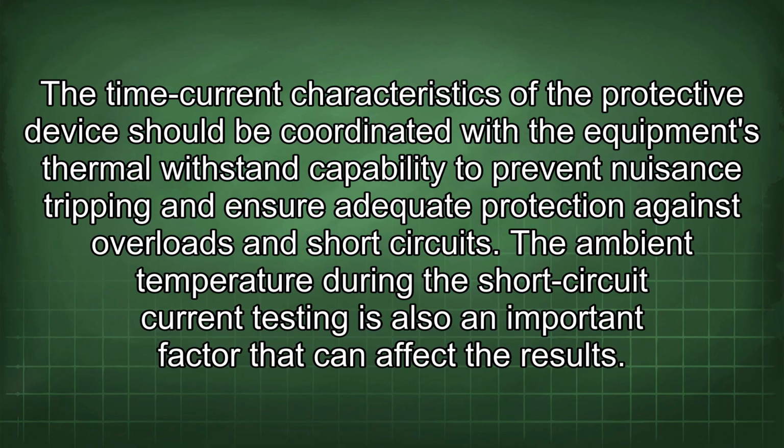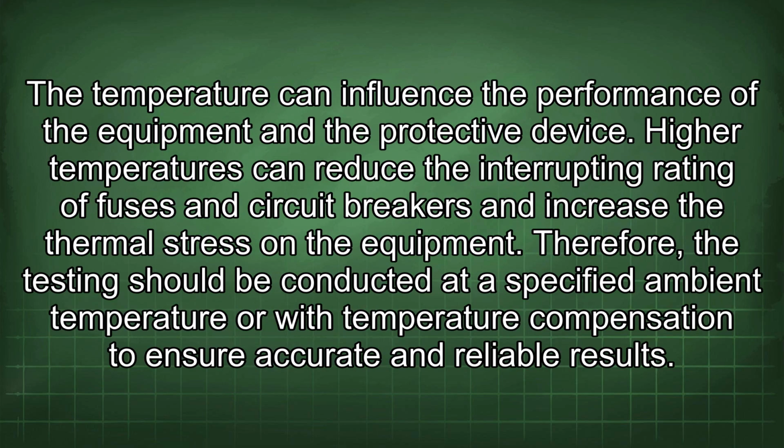The time current characteristics of the protective device should be coordinated with the equipment's thermal withstand capability to prevent nuisance tripping and ensure adequate protection against overloads and short circuits. The ambient temperature during the short circuit current testing is also an important factor that can affect the results. The temperature can influence the performance of the equipment and the protective device. High temperatures can reduce the interrupting rating of fuses and circuit breakers and increase the thermal stress on the equipment. Therefore, the testing should be conducted at a specified ambient temperature or with temperature compensation to ensure accurate and reliable